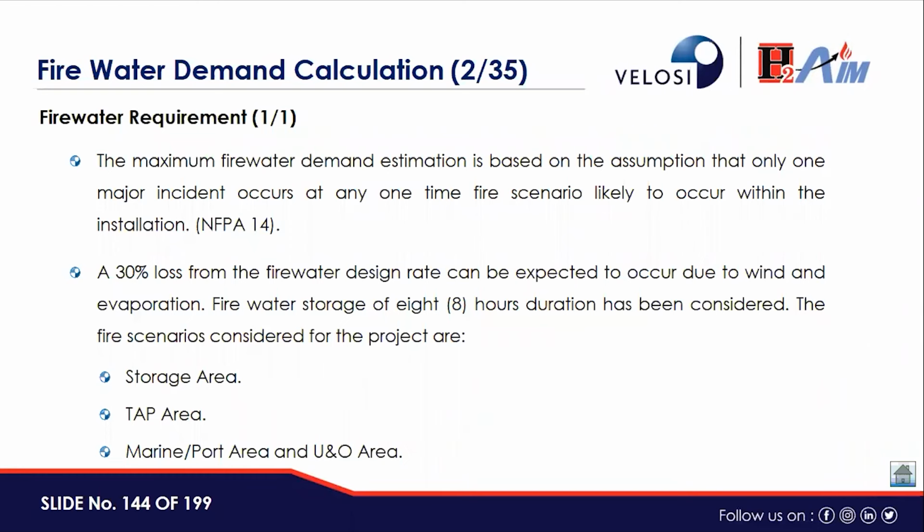30% loss from the fire water design rate can be expected to occur due to wind and evaporation. So this 30%, this type of information we will use in the upcoming slides. We will multiply by 0.3, something like this. So we have to stay focused on these wordings. 30% loss from the fire water design rate can be expected to occur due to wind and evaporation. Fire water storage of 8 hours duration has been considered.